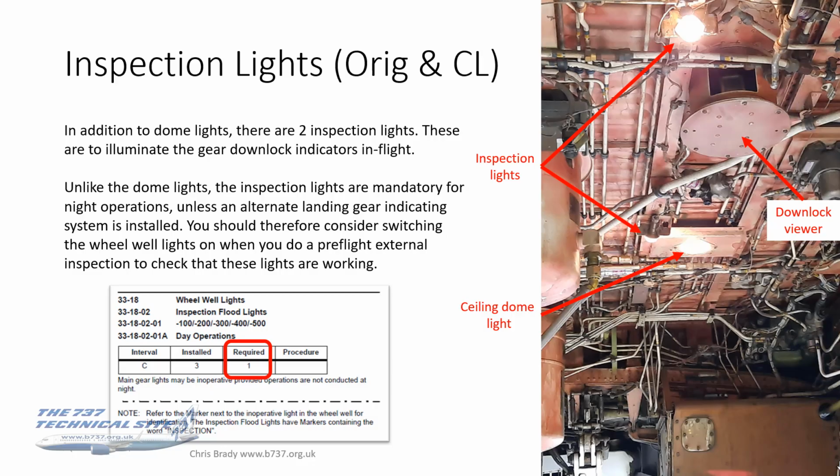Therefore, you should consider putting them on when you do a pre-flight external inspection to check that the lights are working, particularly at night.